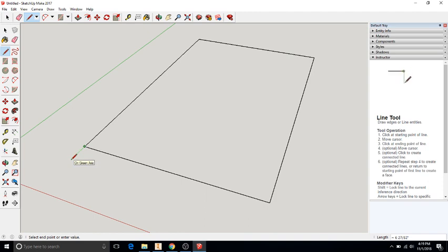I'm going to draw out 3.5 inches. I'm going to draw over 5.5 inches because that's a 2x6, and I did 3.5 to match up with the 2x4 here. Marching around, so I don't have to do the math there, to make it easy on myself, I know that's a 2x4 wall, and sometimes I extend it way past what I need just to make sure the line is green. 3.5, enter, and the red line, 5.5, enter. And you're coming back to connect. So there I have the footprint of my 2x6.